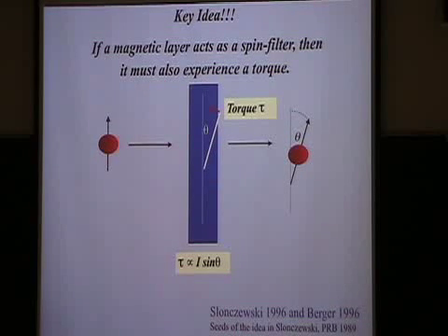There are actually seeds of this idea in a paper that John Slonczewski wrote in 1989. John Slonczewski is a scientist at IBM Research who's worked many years on magnetic materials. He considered a magnetic tunnel junction, two magnetic layers separated by an insulating layer, and he did basically the rectangular barrier calculation for a tunnel junction, and he showed that when you bias the tunnel junction, you change the magnetic coupling between the layers.